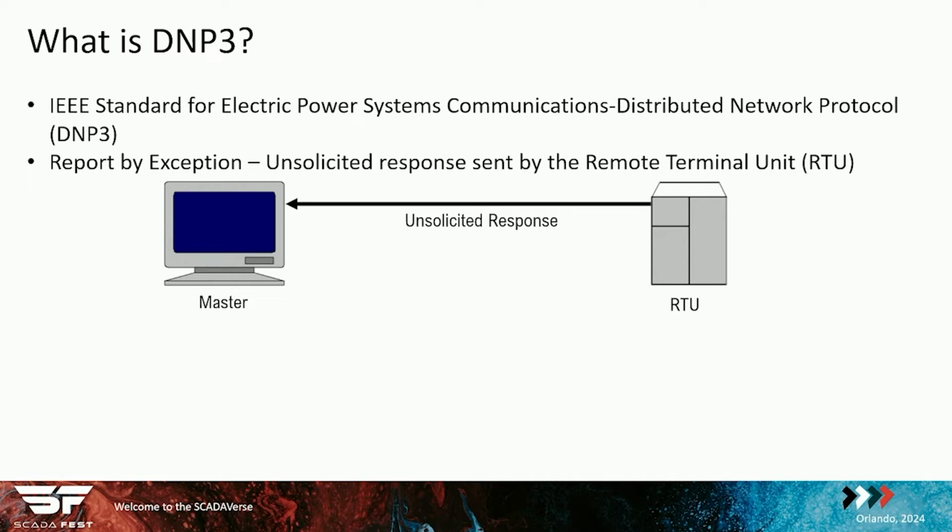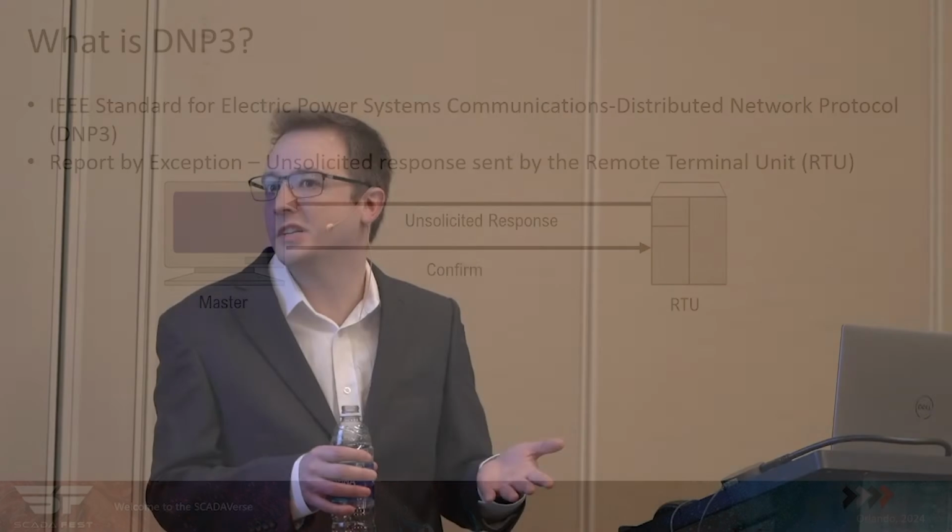We're configured with an open listener port that will accept the data when it comes in from the RTU, and then we do have to send a confirmation response back so the RTU knows we have received the class data. That is part of the protocol, that it expects to receive a confirm so we know we've been reported to. This is in case the communication network link is down, it is going to keep trying until it gets that confirmation from us.